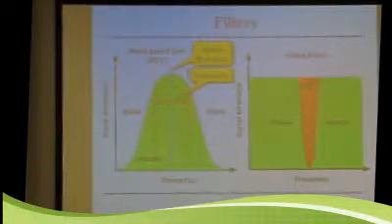Now, a notch filter does a different animal. Let's see what we got here. We've got our 3 kilohertz signal here. What did we say a CW signal is typically? A CW signal is typically like 500 hertz, or 0.5 kilohertz. So if some bad person, through either negligence or being a jerk, decides to tune up in the middle of where you're talking, you've got a little signal interfering with your big signal. If we could just take that little signal out or attenuate it, then we would be able to communicate better with whoever we're trying to talk to.